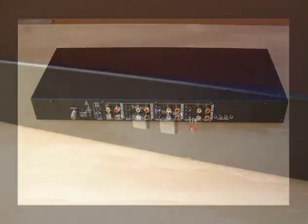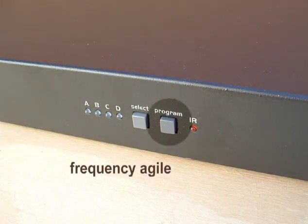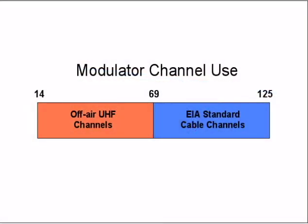Modulators come in a wide range of sizes, features, packaging, and number of inputs, from single-source single-channel to four-source four-channel models. All the modulators you'll be using are frequency agile. That is, you can select the output channel. You need to do this to set the modulator channel to a channel that's not used by local off-air or cable channels. Modulators typically use off-air channels when set at or below channel 69, and EIA standard cable channels when set above 69, although some can be set to IRC or HRC channel plans.